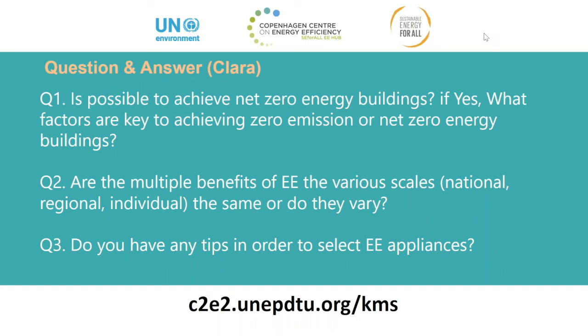And if we talk about what is the key to achieving zero emission buildings, again, I have to stress the idea that was presented in the session, which is, in the case of pre-existing buildings, a very detailed energy audit and understanding of the energy consumption and patterns of the building, in order to know what are the most effective or suitable measures to implement. And in the case of new buildings, of course, a well-designed building would be key to achieving zero emissions.